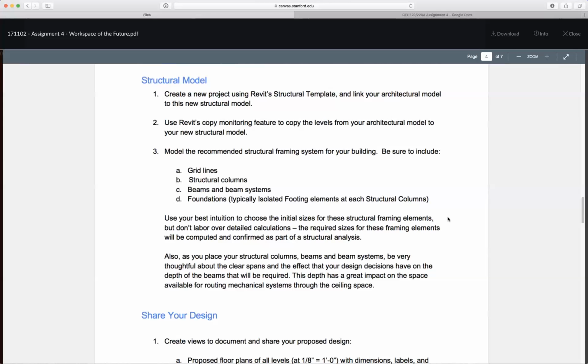We'll do it again today, but it's not so bad. If you can come up with a good system of grid lines and levels for your overall shape and form, putting the elements in is not too hard. It follows a very regular pattern that involves a lot of copying and pasting and repeating things. We'll take a look at that some more today.